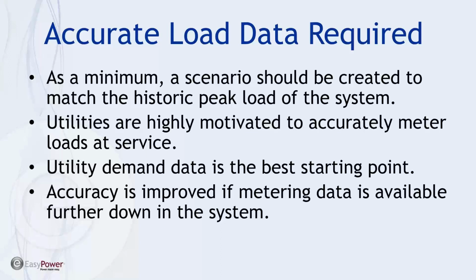For starters, the utility company is very good at delivering data on real and reactive power flow at the point of connection. And so to refine your one-line, as a first order approximation, make sure you have loads that line up with the utility interconnect that the utility company has determined for us.